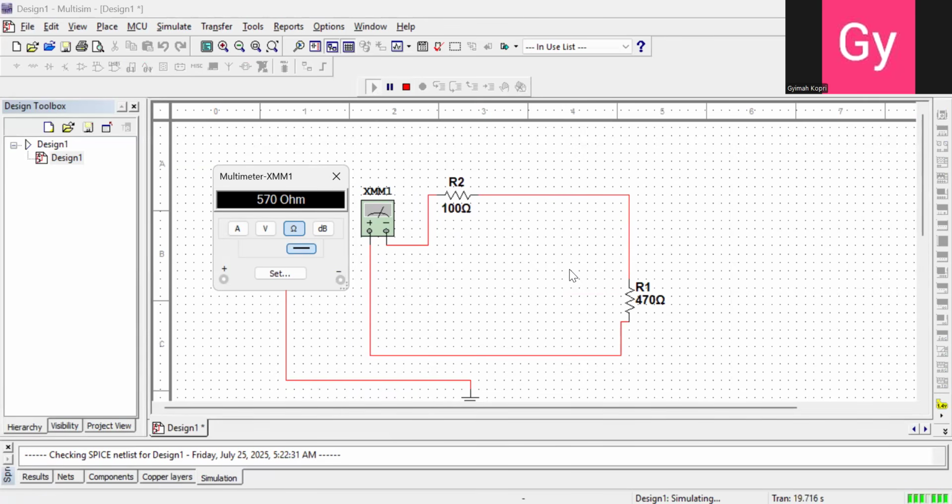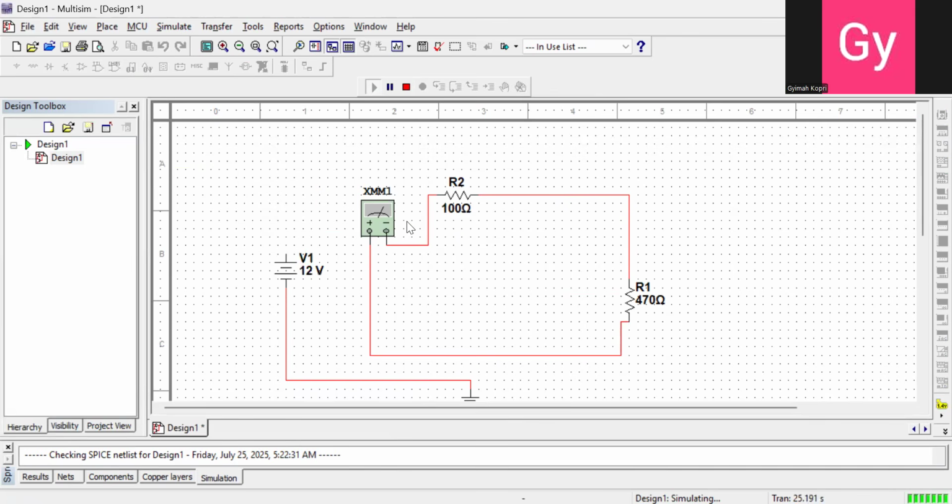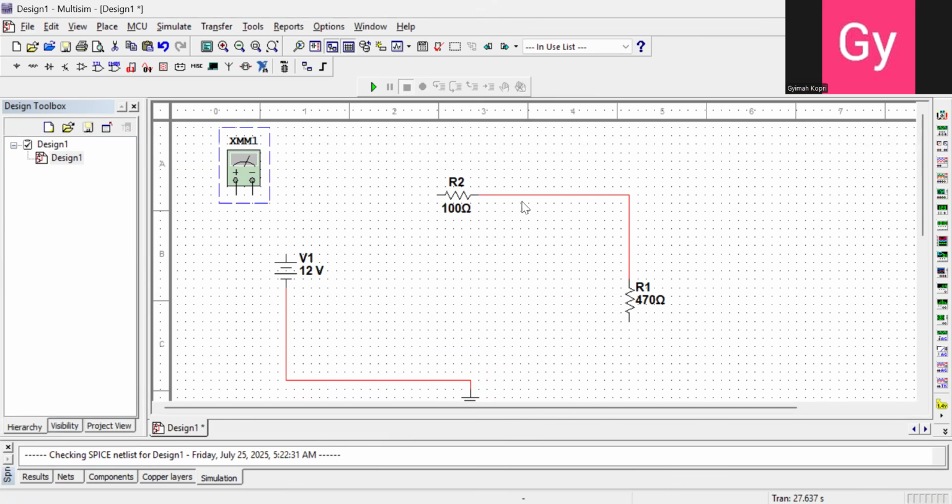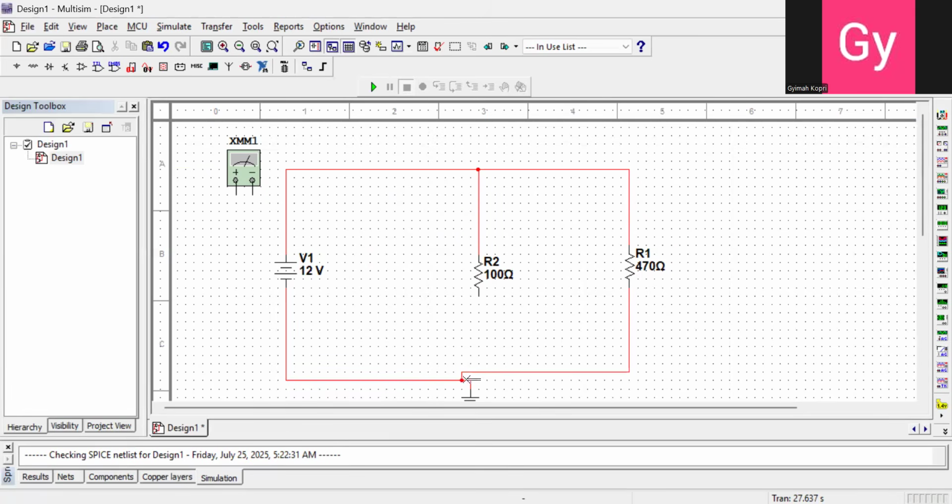Experiment 1B. You measure the total resistance of these 2 resistors, and they are connected in parallel. So let's do that. Let me take off this meter, but let me stop the simulation first. Take off the meter. We have another circuit, of which this one is in parallel with this resistor. I will check the values too. So we have our connection this way. We are seeing head to head, then tail to tail, which tells you that they are now connected in parallel.